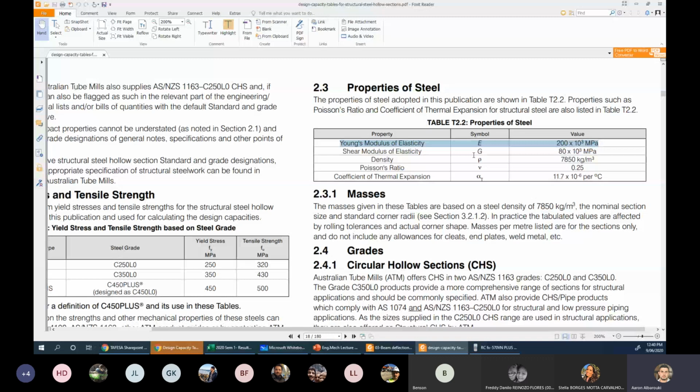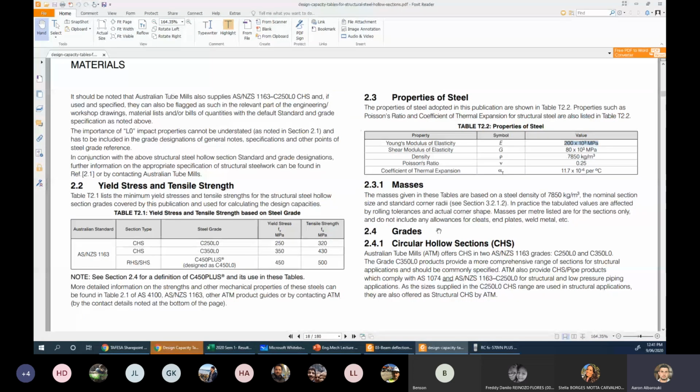So please try to get used to this: when we talk about elastic modulus, this is something given, a known fact. When I say steel, you should straight away think steel has a modulus of elasticity of 200 times 10 to the power 3 megapascals, like when you know gravity acceleration is 9.81. That's the structural steel we use.